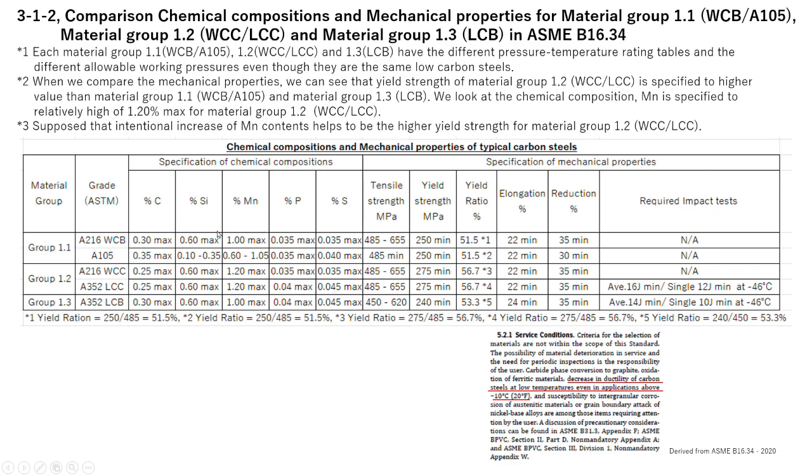So the LCC casting and LCB casting both are low temperature service application material. ASTM A352 material specification requires the low temperature impact test at minus 46 degrees Celsius temperature.